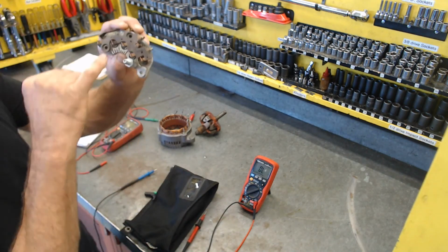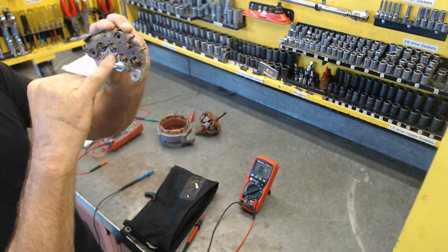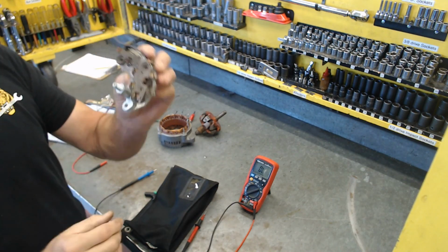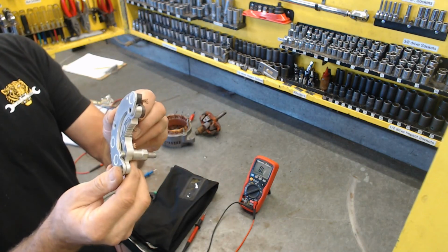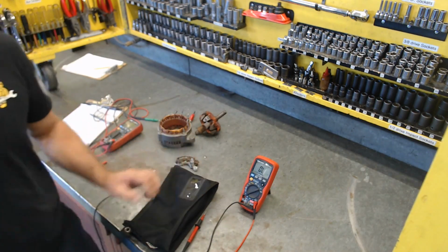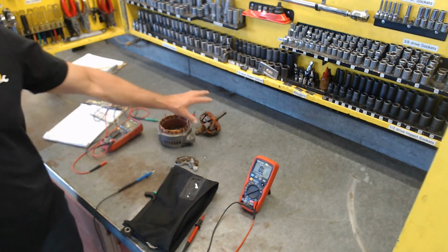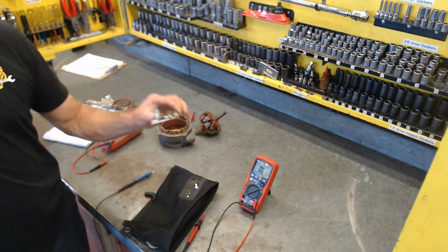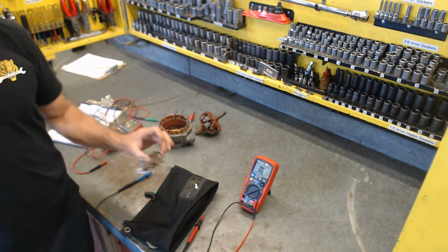And again, I was just checking from that diode there to the base there, or this diode here to its base here, and then swapping the leads. All these diodes are good. There's nothing wrong with these at all. So that shows you how to not only check the rotor and the stator for shorts, etc., but also the